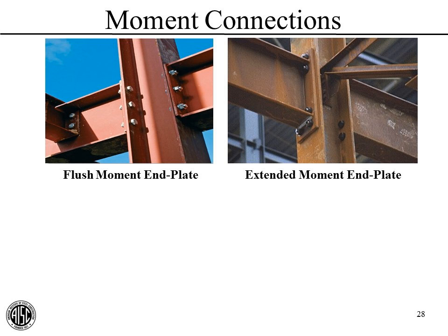All right, here's a couple of pictures of moment in plate connections. This one's a flush moment in plate connection, and you can see that the plate does not extend above the top of the beam nor below the bottom of the beam. So all of the bolts are in here.